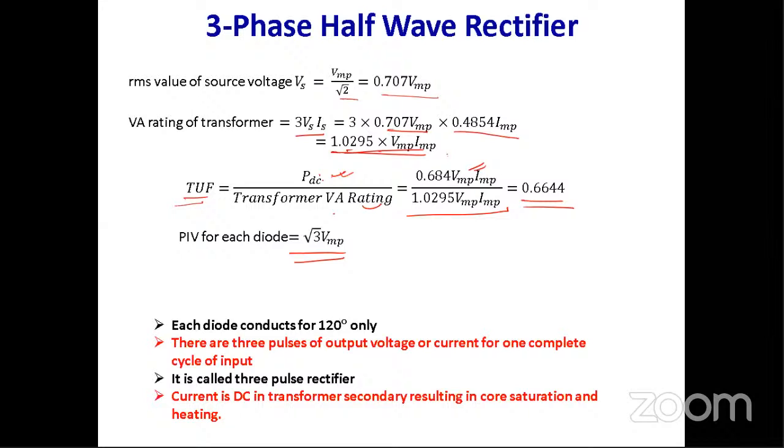Already I mentioned in case of single phase half wave or full wave rectification circuit with resistive load, sometimes we want to know the different factors for this three-phase half wave rectification scheme. All the factors depend on four basic quantities: average output voltage, RMS output voltage, average output current, and RMS output current.